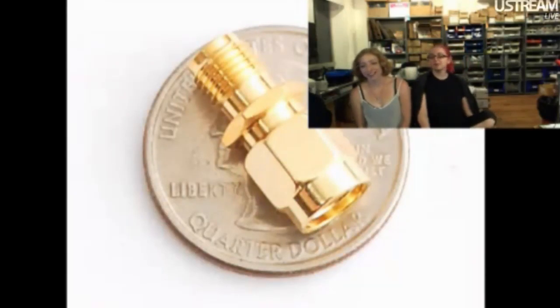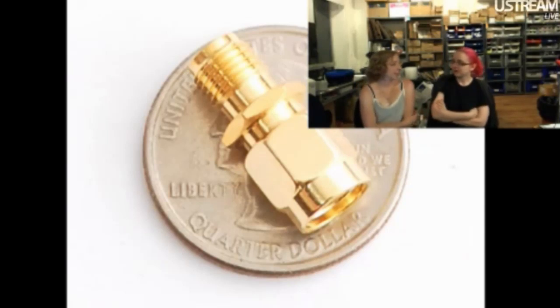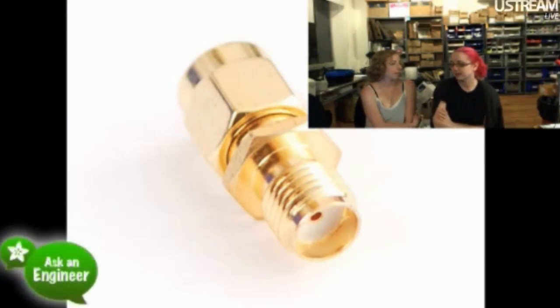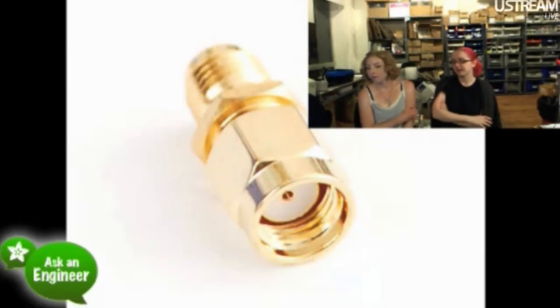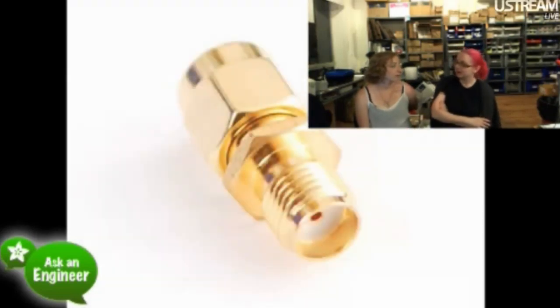What are these things? So these are adapters. They're RF adapters, and basically, if you're doing Wi-Fi, 2.4 gigahertz, the antennas and adapters are all RPSMA, so that looks like that. And if you're doing cellular stuff, you have SMA adapters. But some old Wi-Fi stuff or some high-powered Wi-Fi stuff is SMA. And some cellular antennas you might end up getting are the other way and so on. So basically there's two standards, and this adapter will adapt between the two. So if you want to connect an antenna that's SMA to a Wi-Fi adapter, you can use one. And if you want to use an RPSMA antenna with a cellular thing, you can use the other.